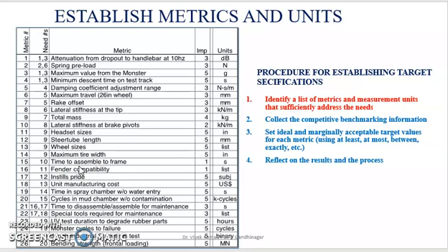Now they have to establish a performance metric list, which is the first step in the procedure for establishing the target specifications. There are 2 methods to perform this activity. The first method is to list down the various metrics or performance indices of a particular product. In the second method, we will establish a mapping between the customer needs and the performance metrics.